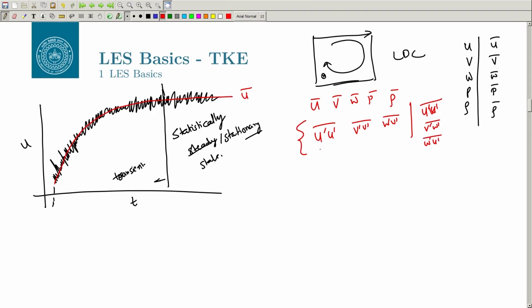If we subtract this u bar from u, what we are going to get is the fluctuating quantity. You can get the fluctuating quantity every time. The best way to get these quantities, u prime v prime bar, is to use the identity that we discussed when we were discussing RANS. Let us say you are not only collecting u bar, v bar, w bar, p bar, rho bar, but you are also collecting other bars.